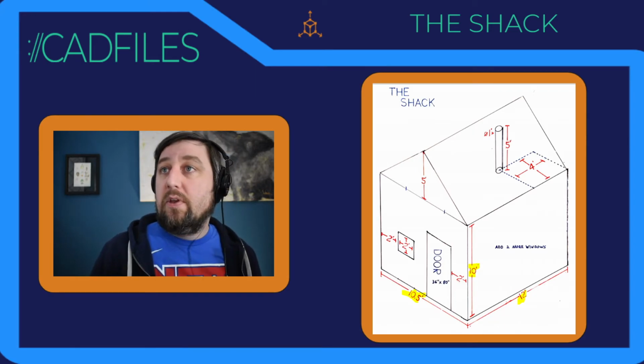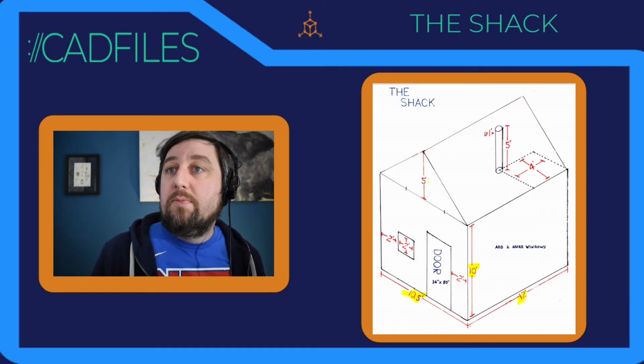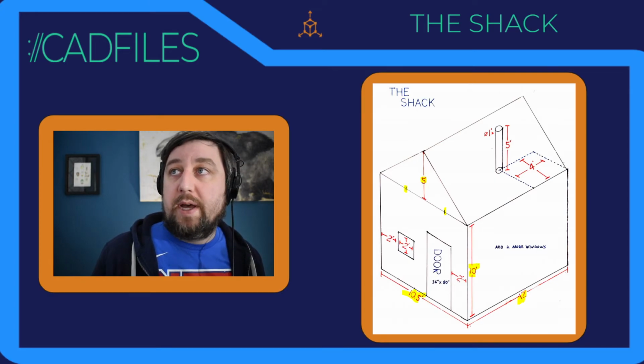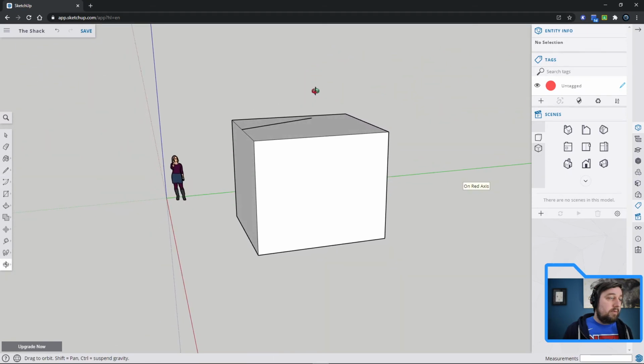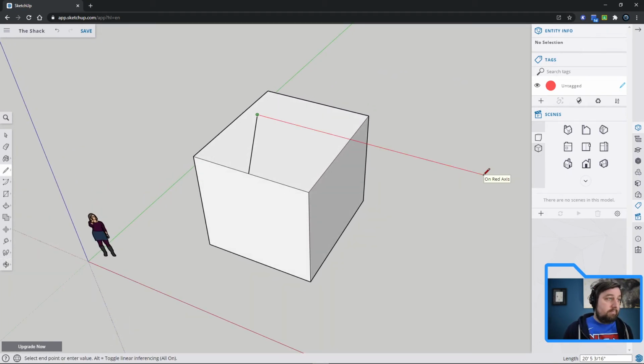All right, so this roof goes up 5 feet, and you'll notice it's at the midpoint. When I have symbols like that in geometry, that means these two lines are equal, midpoint, 5 feet up, triangle back. All right, so this is on here. I want to be looking straight on now to be able to draw this straight back. So if I just started drawing a line, for instance, and I click on the midpoint, look at blue, and I just start going like that, look, it's not helpful. It's not useful. So you got to make sure you're clicking on your face.